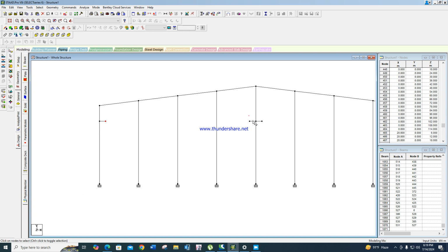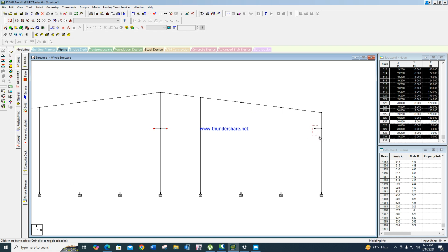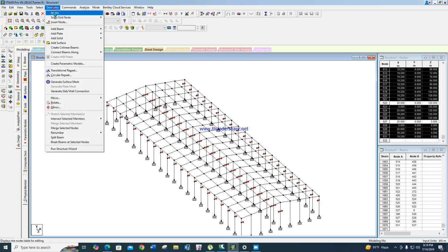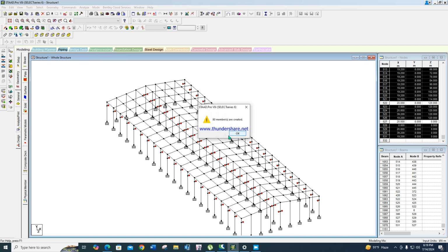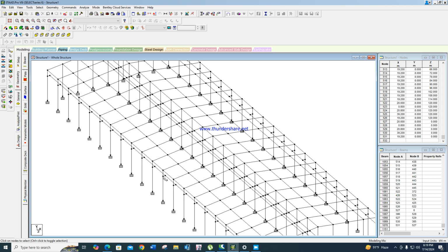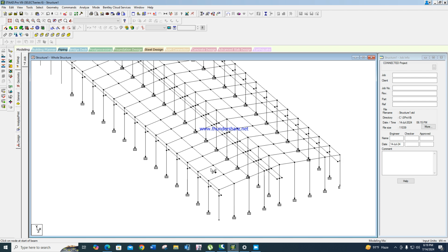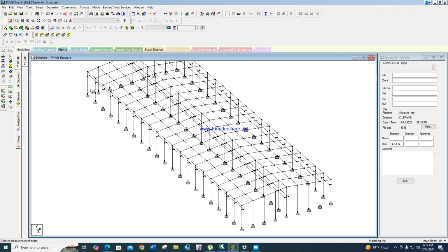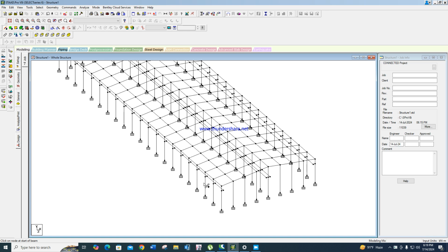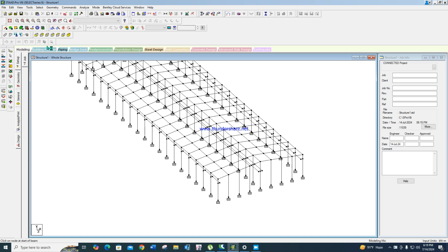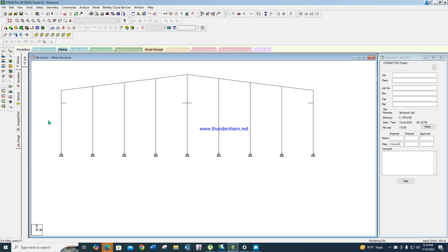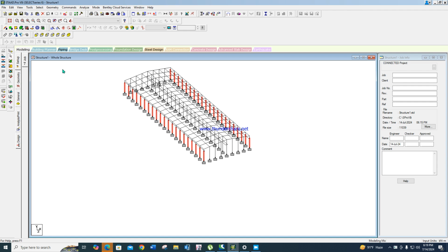Now we want to make the crane beam. Now connect the beam along the z axis. This is the beam or crane beam. Okay. We can use bracing here. We can insert a mid node at the midpoint, so that we can break the bracing point. To use bracing, we insert a node here at the midpoint,